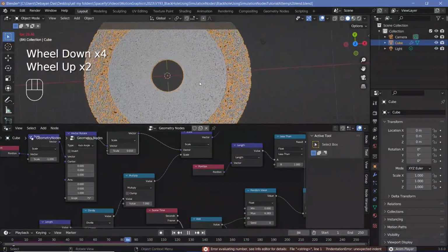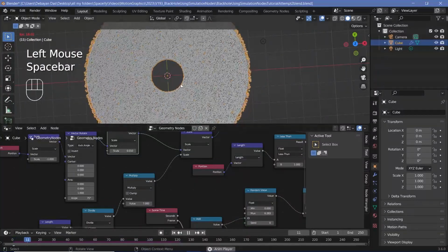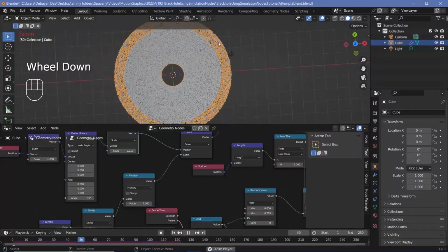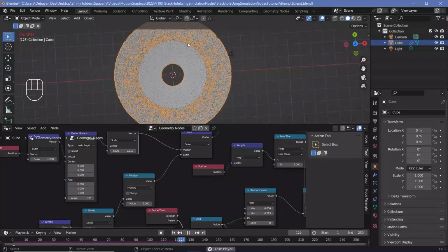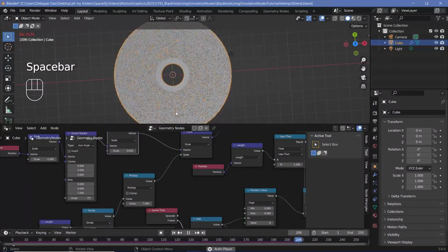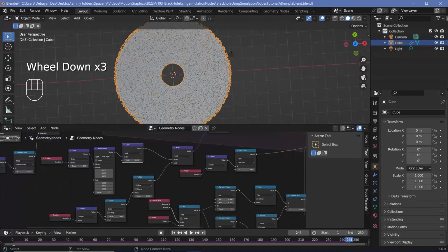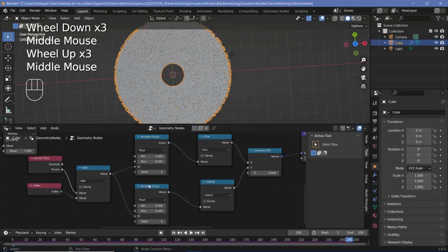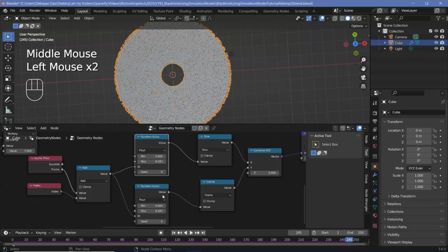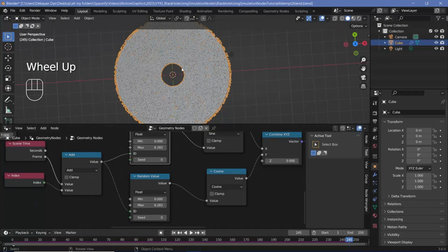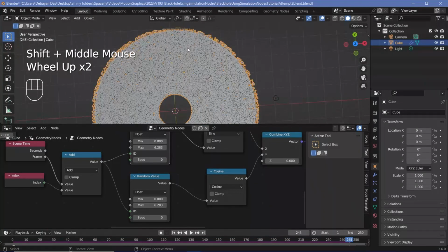However, this still does not look like an actual galaxy, and that's because galaxies have these nice arms that are present around them, and this is just a random distribution about the entire plane. So to create areas with higher densities and regions with lower densities, what we can do is actually change the seed on either the sine or the cosine values. If the seeds are not the same, what will happen is we'll have constructive interference in certain areas and destructive interference in other areas. So some areas will keep getting more number of particles and some areas will keep getting lesser number of particles due to the nature of sine and cos.